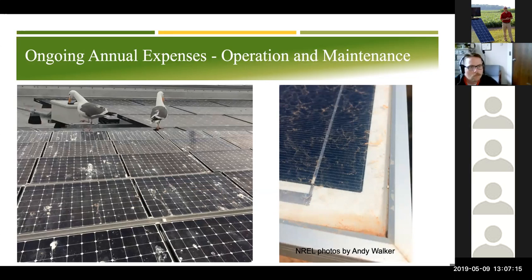This is a picture from the National Renewable Energy Lab report illustrating why you may want to clean the panels. Honestly, with the system John showed an image of up at Stone Laboratory on Gibraltar Island, we have a lot of seagulls and birds up there, so we see some panels that look like this from time to time. This is an example of a system that was near a construction site. Based on the NREL report, there was a 5% production loss while these panels were operating with silt on the modules versus after they were cleaned.